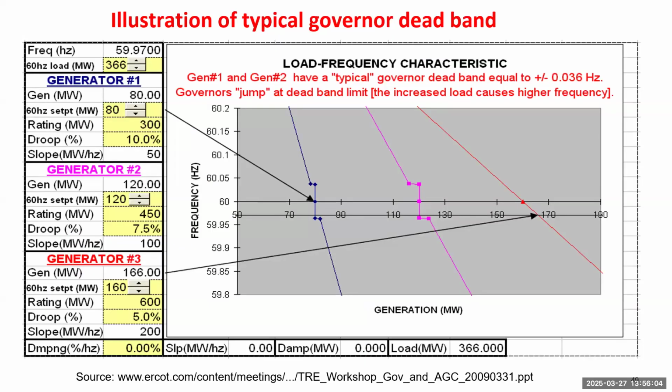So we have 2 additional slides. I just want to give you an idea of how the generations are scheduled and frequency is regulated in real time. This doesn't accurately represent the user interface of operators, but I borrowed these slides from training slides. The training slides are for old operators to teach them how to regulate generation, how to adjust the droop control factors, and how to consider the dead band of generators. So you can treat this almost the same as the software interface of operators.